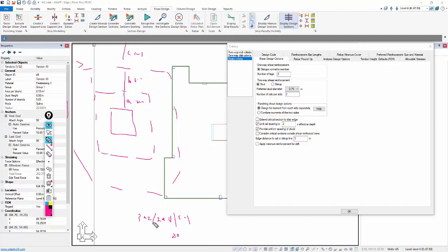So now I might need, instead of 3, 2, and 5, which is 10 studs, I might need 16 studs. Actually, this would be maybe 19 studs, 19 at 1 to get the 20 inch length. So this will normally end up in having more studs in order to meet the uniform spacing, the way we handle that, versus just the direct outcome of the solution, where you could technically have different levels and increments of spacing.